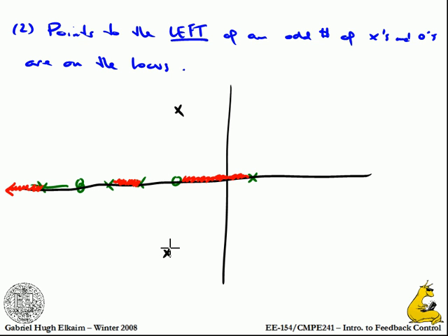Yeah, Andrew. Is this similar to branch cuts and analysis? No. We're strictly evaluating the phase of complex numbers. It's sort of a philosophical point: all we're doing is looking at the phase of a complex number, and that complex number is a ratio of complex polynomials, which we don't really care about. As soon as we can factor them, we can essentially evaluate the phase graphically, and by evaluating it graphically, we can get huge amounts of information out of the system.